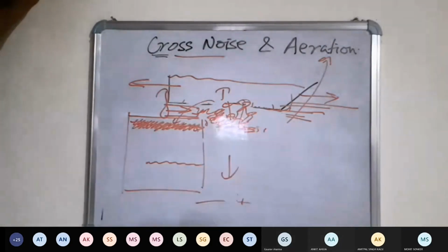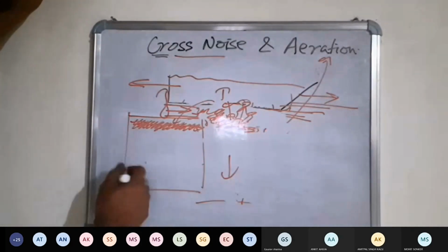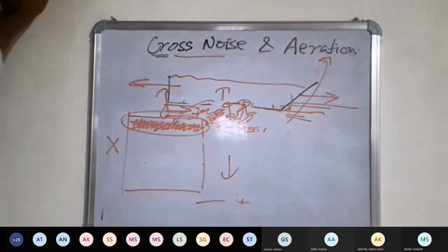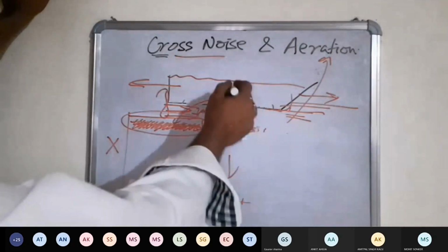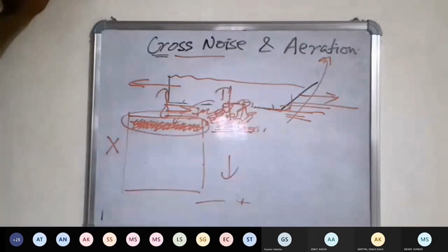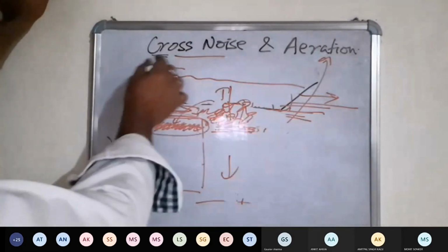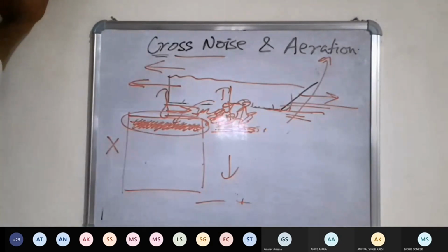Nothing goes to this side. In that case, the echo sounder stops working. Only at the zero line there will be a dark line, because the signal is not able to penetrate this. So depth reading will be stopped. Ship going astern, echo sounder does not work so very often.